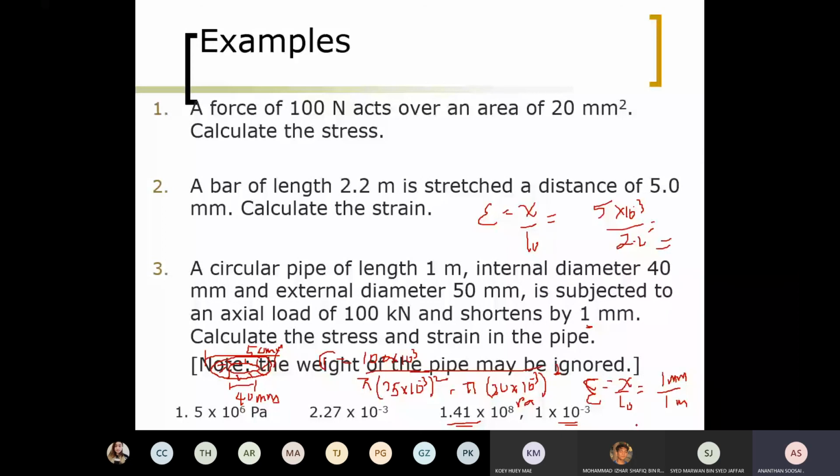So this is today's lesson. Today you learned about Hooke's law, springs connected in series and parallel, then two new terms called stress and strain. What is stress? Stress is force per unit cross-sectional area of a material. Strain is the ratio of extension to the original length. Stress causes strain. Unit for stress is Pascal. Unit for strain is unitless. Big stress is going to yield a big strain.